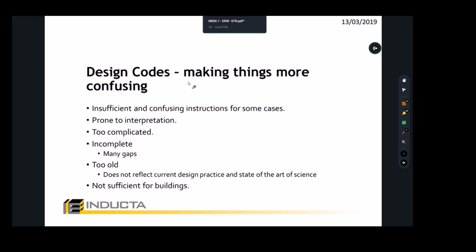It's like engineers trying to have an agreement about what factors to use to determine earthquake loads in a Melbourne-like area. There are many factors. If you are designing a building in Melbourne, you have to use this factor of acceleration. If you are designing over rock soil, you have to use this spectrum analysis. So that's what the standards do. They make sure engineers who practice in this area, under this environment, all use those parameters. And by law, you have to use them. If you did not, then you did something wrong with your license.